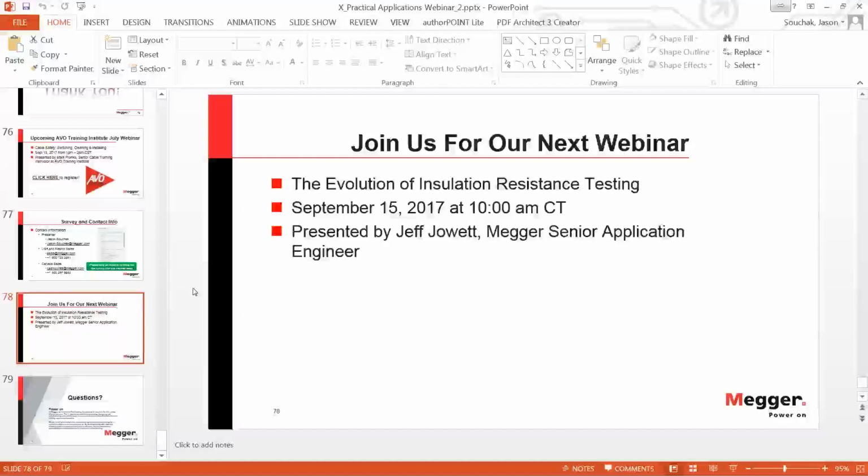Okay, you can also look at leakage current. If you use the cosine rectangular VLF unit, you can do a withstand test with leakage current, or you can do a monitored withstand test. The monitored withstand test, in my opinion, is a very great tool for a commissioning test, because you do a withstand test at a fairly high voltage, 3 per unit, the highest test voltage that we use. You look at the PD level at that voltage level, and you can also see whether you have any leakage.